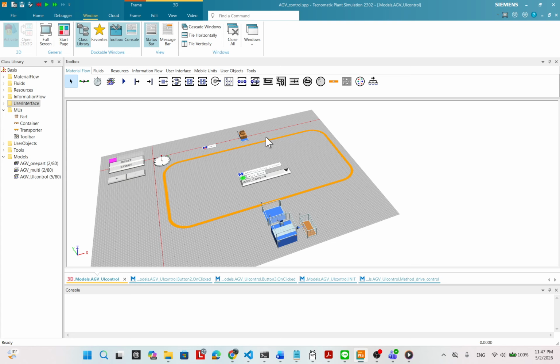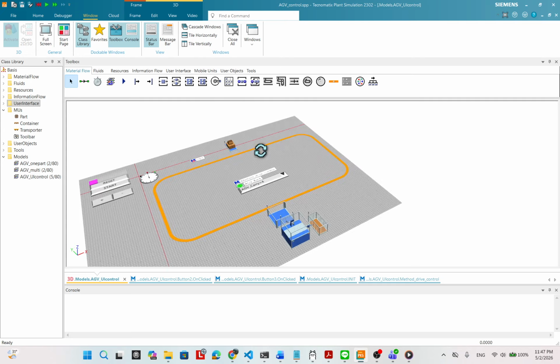You can press start at the default position. You press start and already have the AGV at the location you need to specify for it, and use backward and forward, right? In the normal way you could not use the backward, right? The backward and forward controls the direction of the AGV moving forward and backward. And if you never use the Simtalk, you cannot do that, right? You cannot do that.